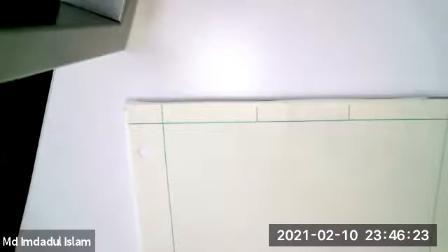But in some ways, those are not really beams. How do you define a beam? A beam is something that's long relative to its height and in-plane dimensions. So when the height is actually bigger than the length, it's not really beam theory. You're using a questionable approximation when you do that anyway.